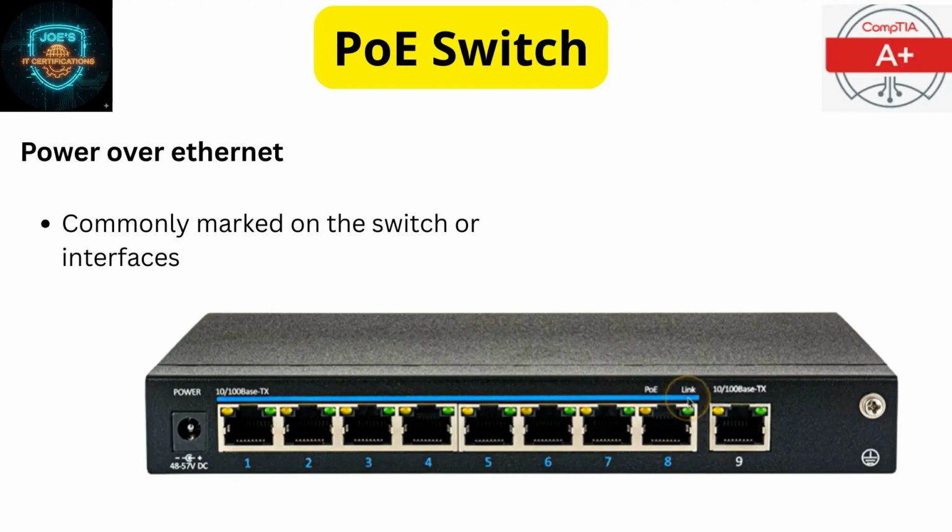but if your switch doesn't support any type of PoE, you can use an injector, like the one you see here. You would disconnect your Ethernet cable, put the injector in the middle, and then plug the injector into a power source to provide PoE over that connection. When the PoE power is coming from the switch itself, we refer to that as an end span, and if you're using an injector, it's referred to as a mid span.